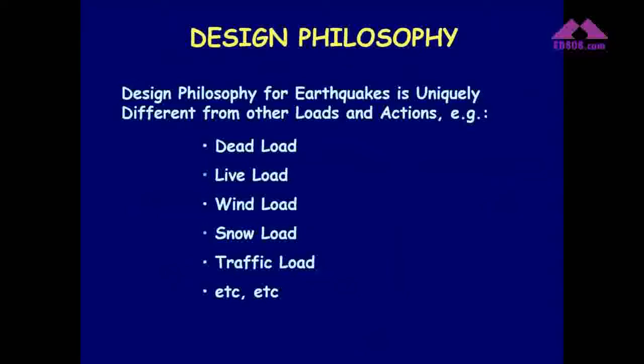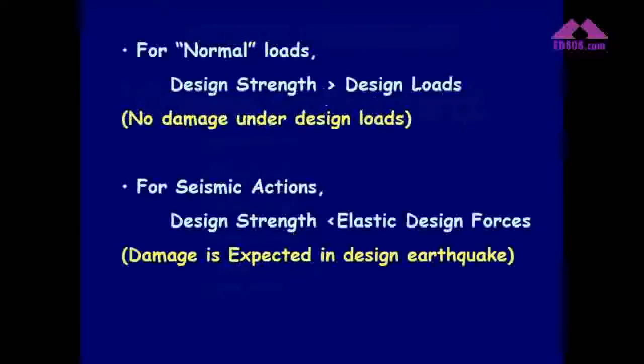The earthquake loads, seismic loads, are a lot different than the other actions, the general loads, what I mean, the dead load, the live load. Live load means us, the furniture, everything that can be shifted in the building, change place in the building. The wind load, snow load, thermal load. The earthquake loads are different than these. Why are they different?